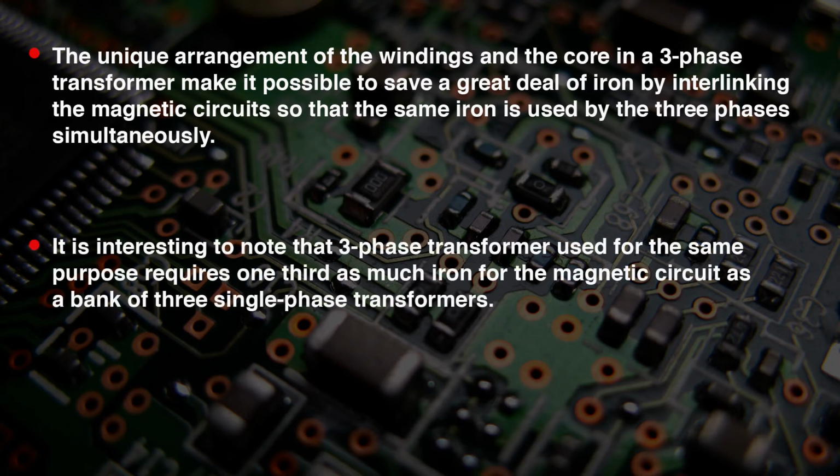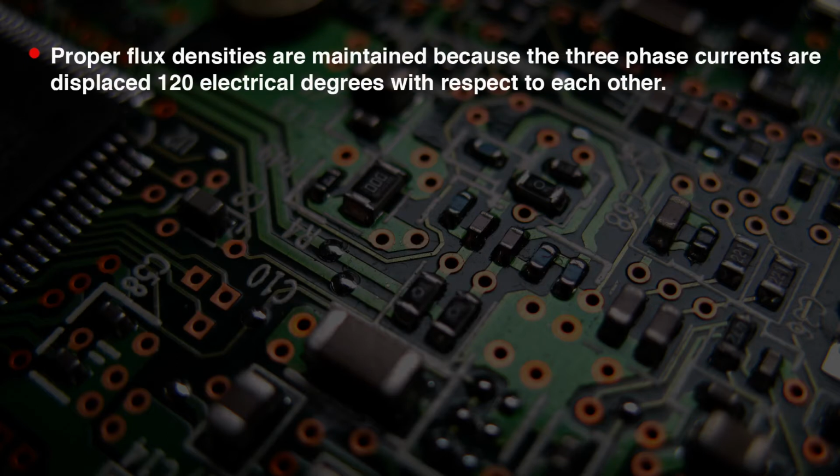It is interesting to note that a three-phase transformer used for the same purpose requires one-third as much iron for the magnetic circuit as a bank of three single-phase transformers. Proper flux densities are maintained because the three-phase currents are displaced 120 electrical degrees with respect to each other.